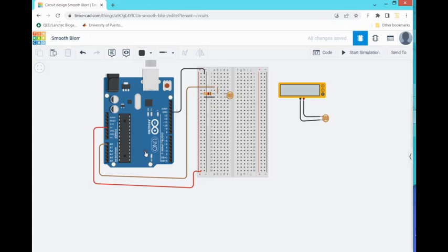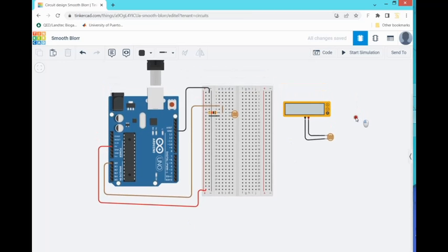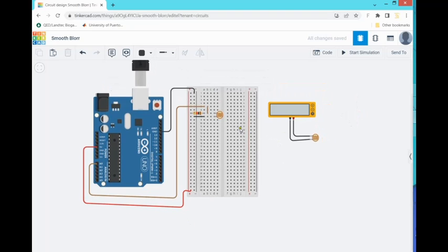So let's move to Tinkercad, and I'm right here. In Tinkercad, I have set up that diagram. You can see the photoresistor right here, and one of the legs of the photoresistor is going right to ground. The other leg is going to the 5 volts. So here's the 5 volt. This is resistor 1 going through the photoresistor, eventually getting into the ground.